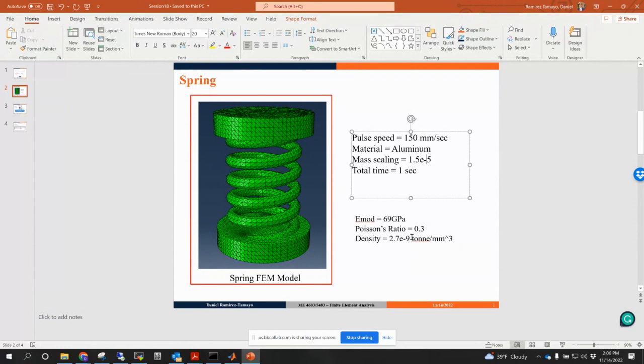displacements. What is the derivative of the displacements? Speed, right? If you derive displacement with respect to time, it's speed. And what's the second derivative of the displacements? Acceleration. So now we're going to solve the continuity equation that has acceleration, velocity, and displacements. All right? Quick intro to finite element, okay? But I just care about the modeling, and that if some of you are planning to do some dynamic analysis, this is a little bit of an intro, all right?